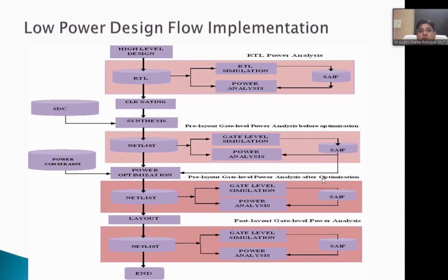The first ones are at the floor planning stage, at the beginning level. To estimate the accurate and actual power we need the layout design. The estimate tells what the power would be, or the battery requirement of the devices, and the actual power is decided at post-layout design.